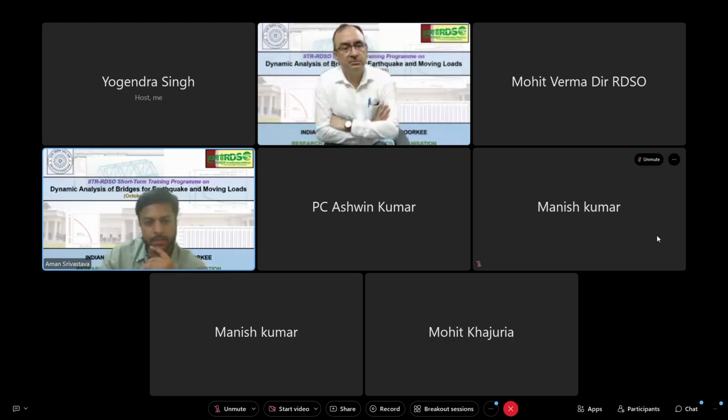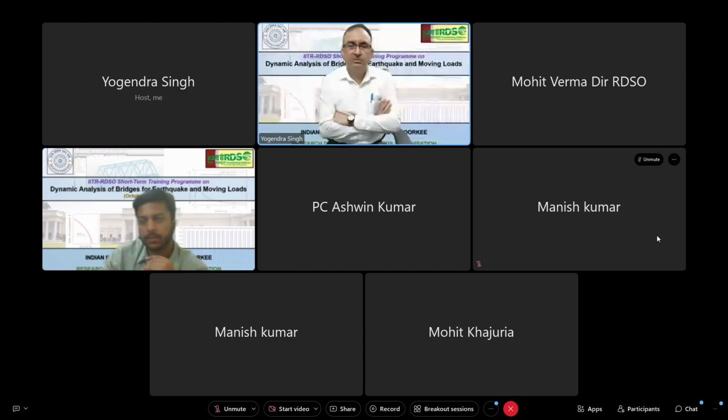Okay, sir. Mr. Jay is asking, to get mass participation factor of greater than 90%, we can also go for Ritz vector analysis rather than eigenvalue analysis. So thank you for providing this information. I should have also included that. Sometimes the eigenvectors which we are getting in usual modal analysis, these eigenmodes cannot provide us 90% mass participation, but Ritz vectors can provide. In that case, we can go for Ritz vectors. That is allowed.